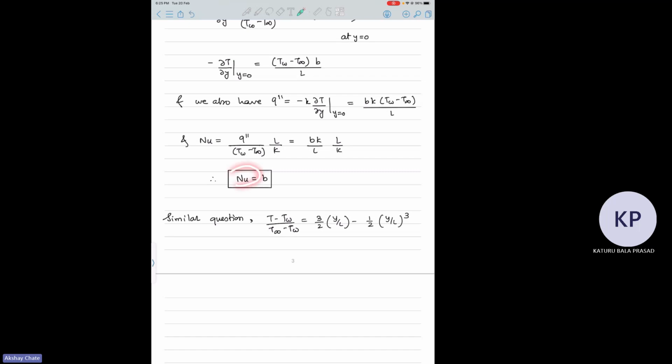And what they do is come up with some sort of expressions for the Nusselt number, and that will be a function of some 2-3 parameters, such as flow velocity, density of the fluid, dynamic viscosity, kinematic viscosity, all those things. Then you get a correlation for the Nusselt number as some function, and you directly use that, and you get H L by K as the Nusselt number definition, and then you get the H. Basically, that is how the standard process is. But we'll not discuss that today. We'll discuss it in the next class. So that is that.